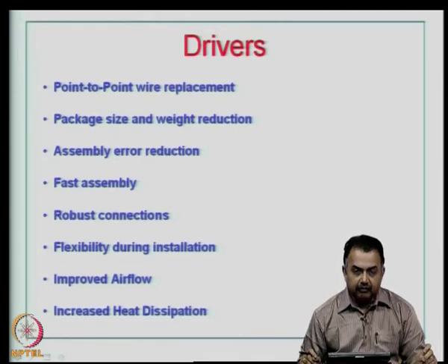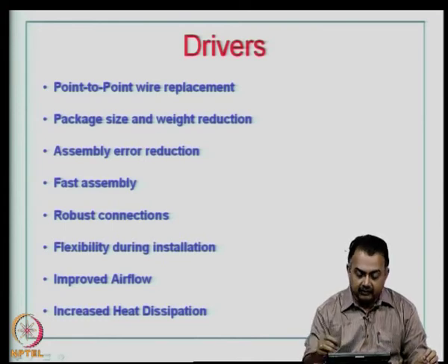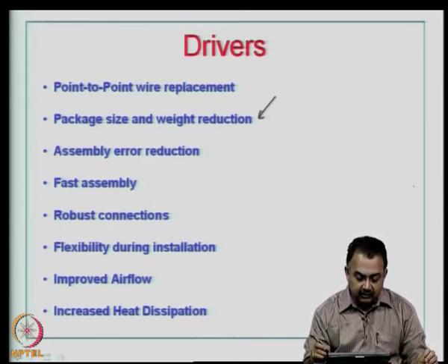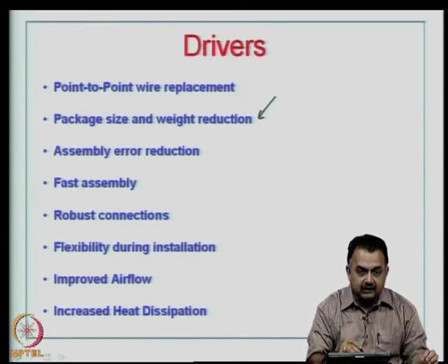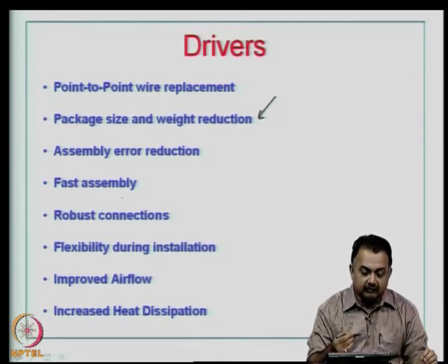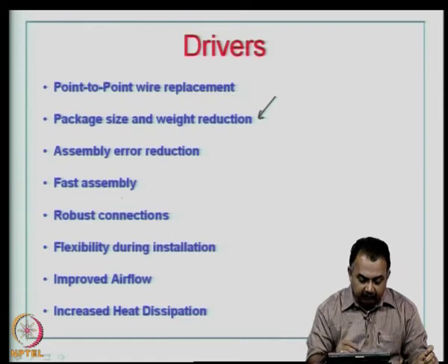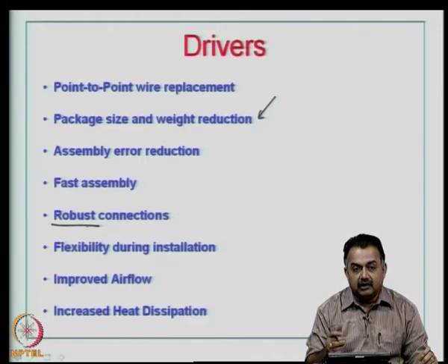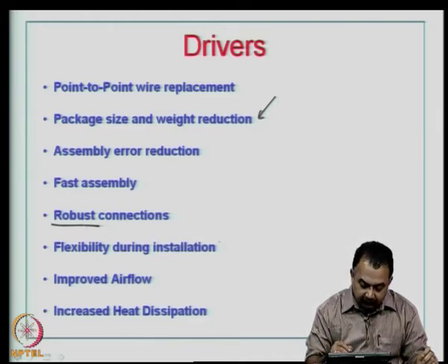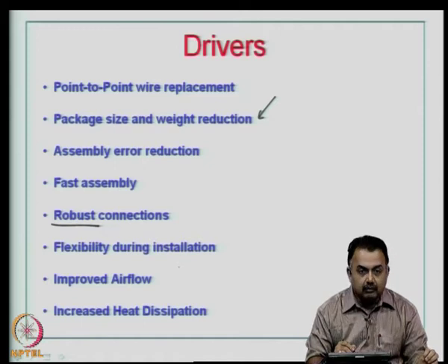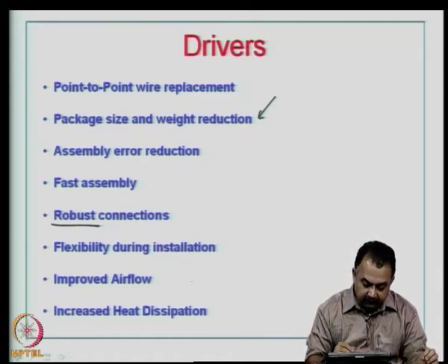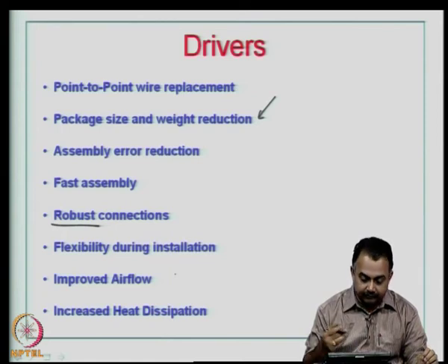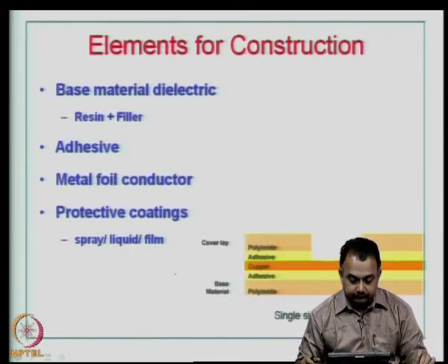The drivers for flex circuits are point to point wire replacement, package size and weight reduction, again a very important point, assembly error reduction, fast assembly, because you do not have to deal with bulky wires, you need to deal with some kind of strips. They are in fact very robust, although they are flexible, thin and lightweight, the connections are robust. Flexibility during installation, improved airflow and heat dissipation in devices where flex circuits are used compared to rigid boards.